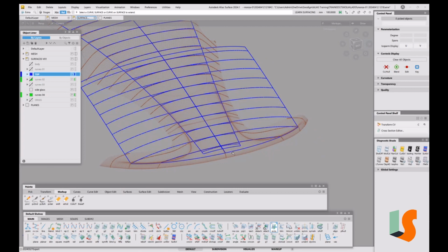The problem is if I took it to the back edge and then aligned it to this edge here, which I could do in G0, and then I could trim convert this surface to this edge. I don't like that idea because it would be difficult to control the shape from this surface to that one. I'd rather have the back edge, the whole of this area, defined by this big block because it's nice and simple. We have less likely problem with trying to transition this way. So I'm intending to trim and convert this back somewhere, but I don't know where yet.